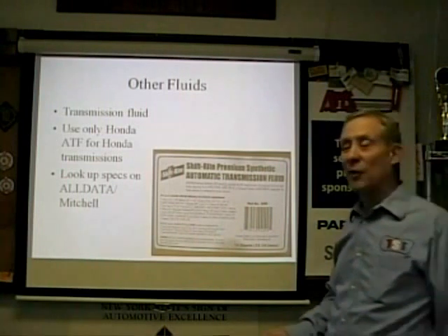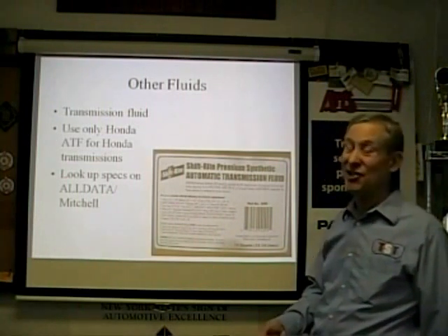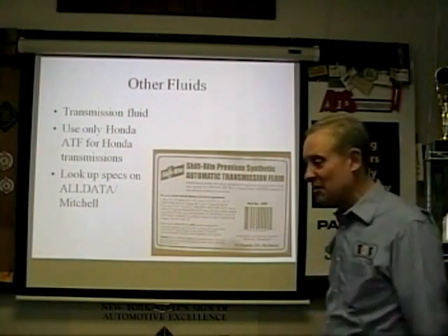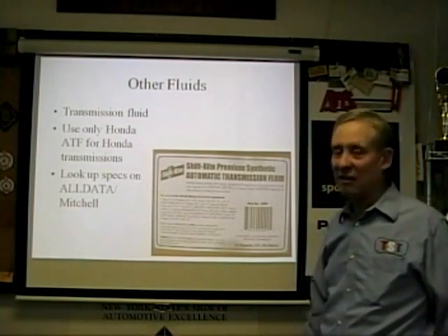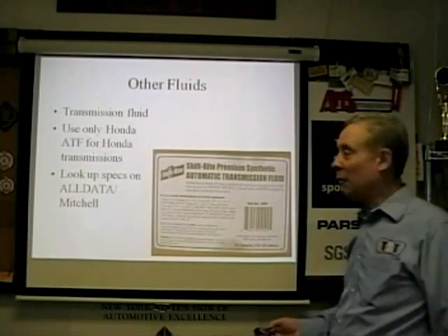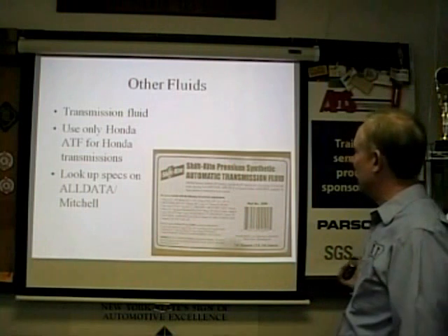In my current Volkswagen world, that's true of the DSG transmissions as well. That's their standard automatic transmission, and those babies are picky, and we've been changing valve bodies, so you don't want to play with it. You've got to put the VW fluid in that case.